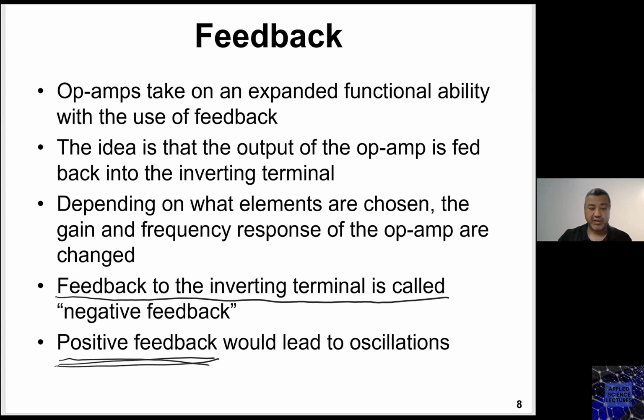As a result, the output would be oscillating, creating an oscillating signal at the output that is not going to help me, at least in my focus on the operational amplifier. Those could be used for other applications, like a comparator, when I compare two signals and I would like to have a highly accelerated output reaching the maximum.